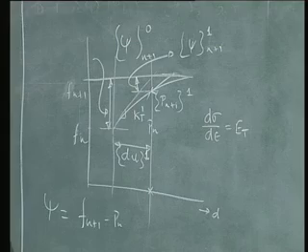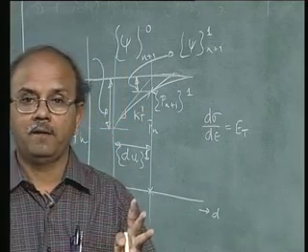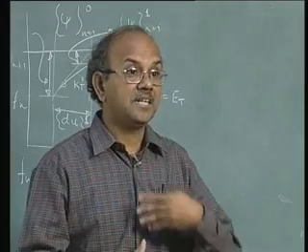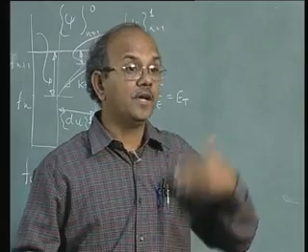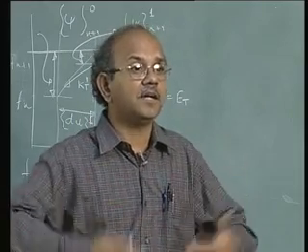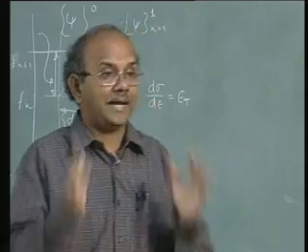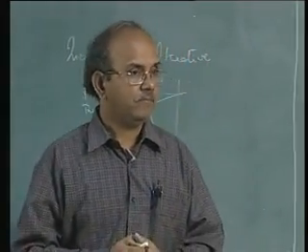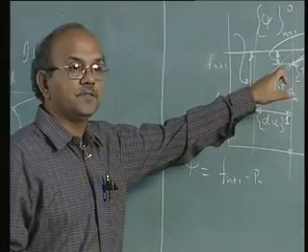So that's what I made a comment, if you remember in the last class itself. Look at the enormity of the problem. Kt in a large problem is like forming the stiffness matrix. Okay, so again you form the stiffness matrix. Again and again you are going to solve the same problem. It looks like that, and so the time required for a nonlinear problem is very high. Right, your observation is very correct that we need to calculate the stiffness matrix again.